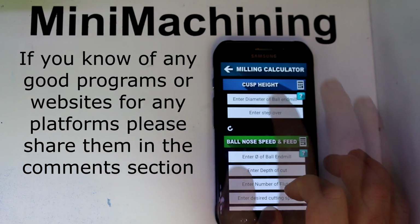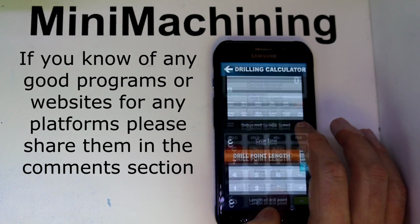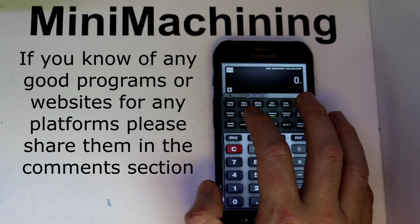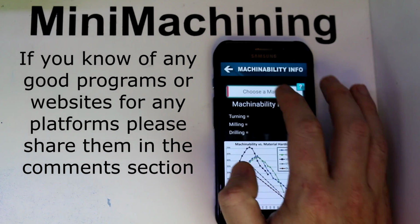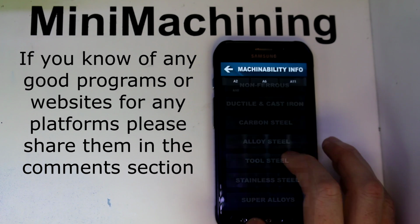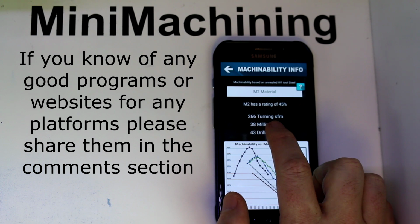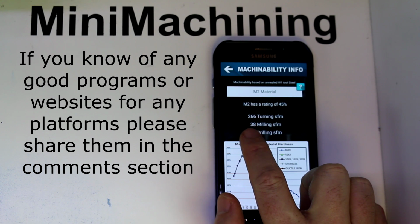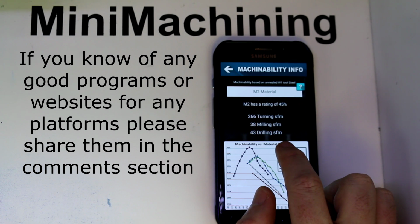Here we have various milling, and then drilling. And then these will also have some references. So here we can choose a material. So let's go with, let's say, an M2 tool steel, and this will give us our turning SFM, our milling SFM, and our drilling SFM.